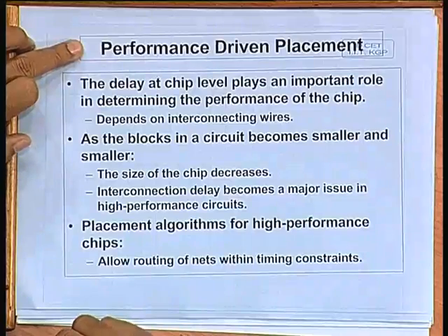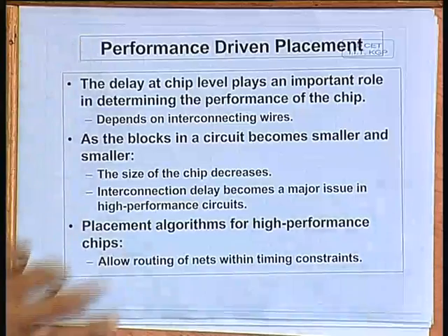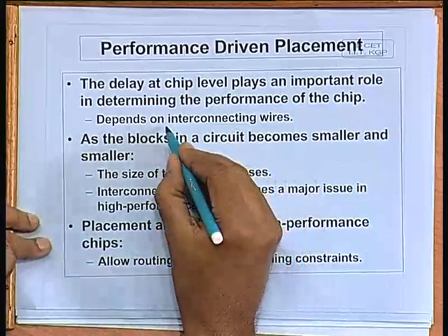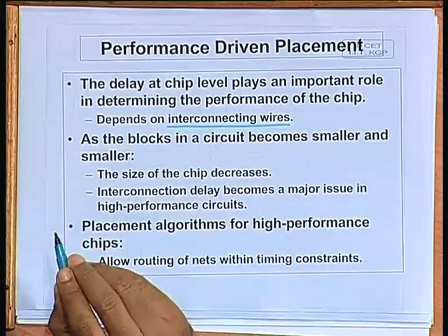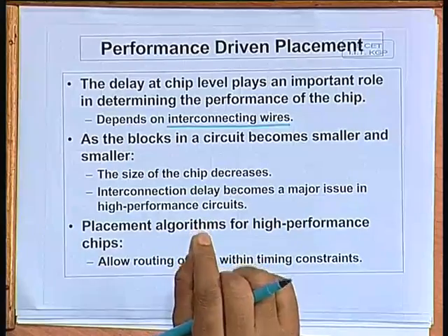Now, there are actually many works which have been reported also, which can be broadly categorized into something called performance driven placement. Well, we are not only worried about the area, we are not only worried about the total interconnection length, but also the overall performance. So, here we are giving more emphasis on interconnecting wires and their lengths, in particular the critical nets.